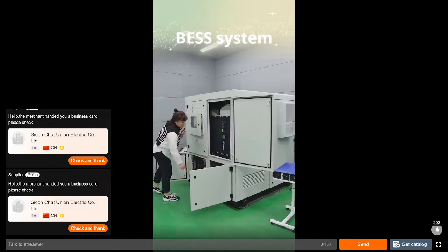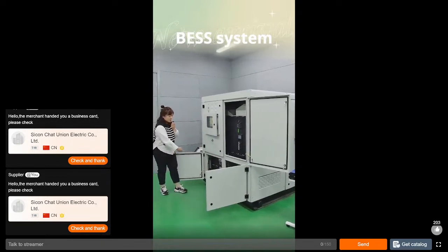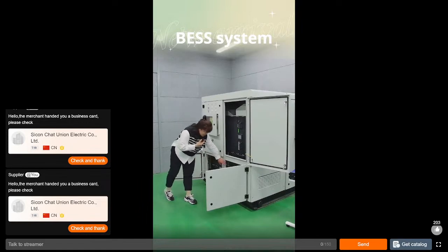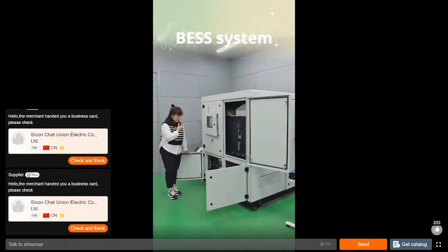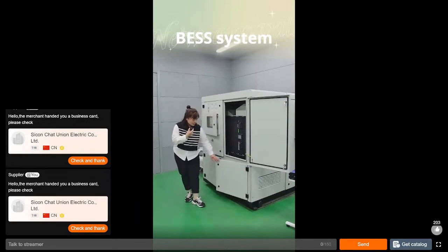This is the next part of the electrical cabinet. This part is for the connectors. As you can see, there are the AC output and AC input. Also there is the SPD protection, and this is the PV connector and battery connector. There are different breakers here. And for the internal cables, we have almost finished on our side. After you receive the goods, you just connect the AC output and AC input cables. Okay, this is the electrical cabinet.